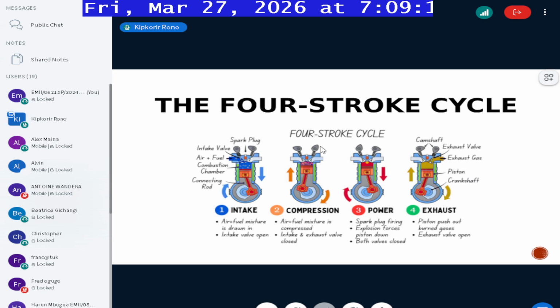So usually a few degrees before BDC, the exhaust valve will start opening, and some gases of combustion will rush out, because usually at that point there is too much pressure created in the combusting gases that when the exhaust valve opens, just for a tiny fraction, most of those exhaust gases will be expelled.